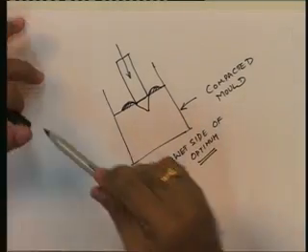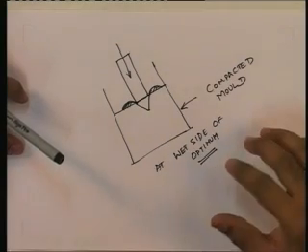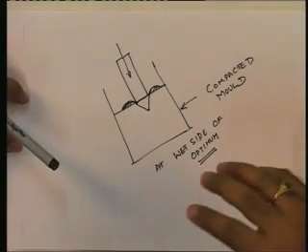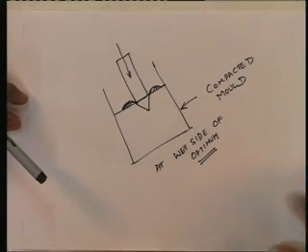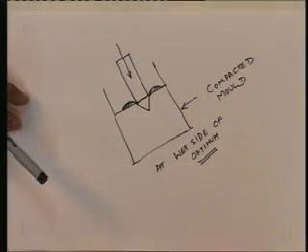So, during this compaction process, before the energy is transferred to the particles to arrange them into dense positions, the soil fails, and in the process the energy gets dissipated in futile bumping. This is a typical bumping, shown here with failures like this.